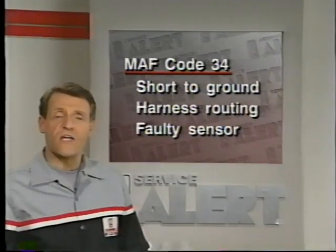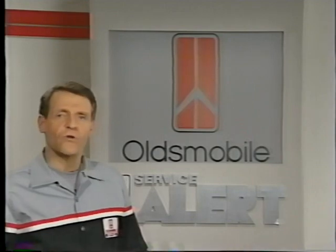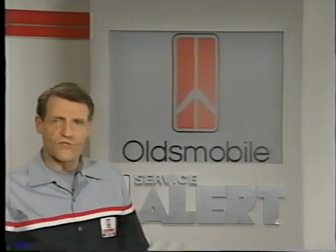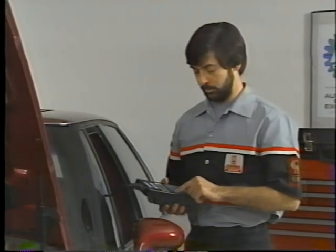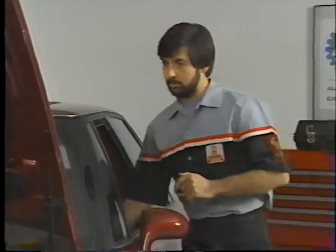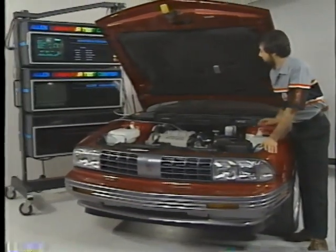In most cases, the engine will continue to run with a fault in the MAF circuit. The controller can use a default value as a substitute for the real MAF signal. Although the engine runs, the service engine soon light would come on, and you would most likely notice some drivability problems. To check a MAF sensor, hook up a scan tool and look for trouble codes. If you find a code 33 or 34, follow the instructions in section 6E of the service manual.